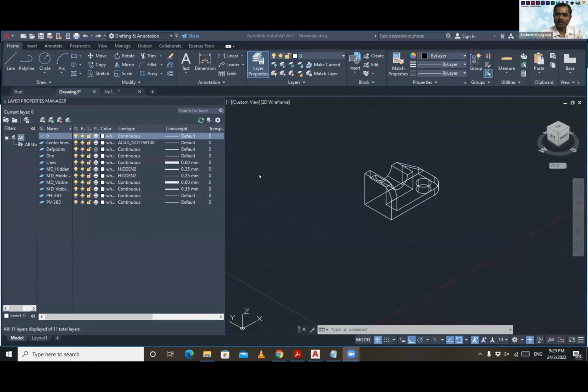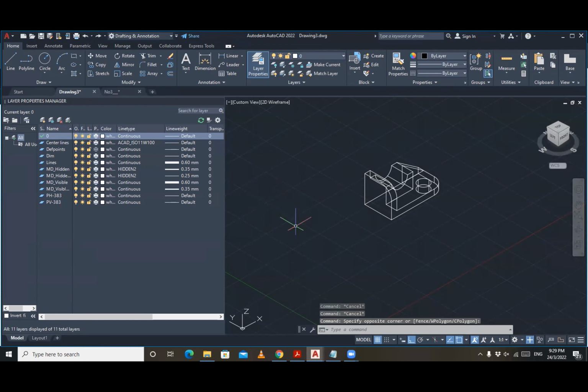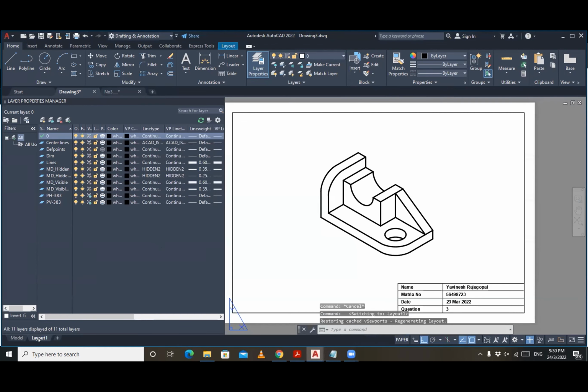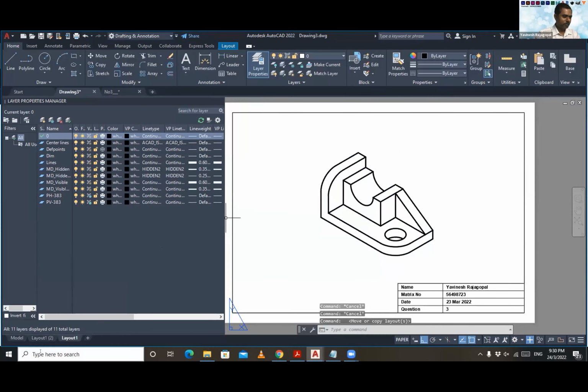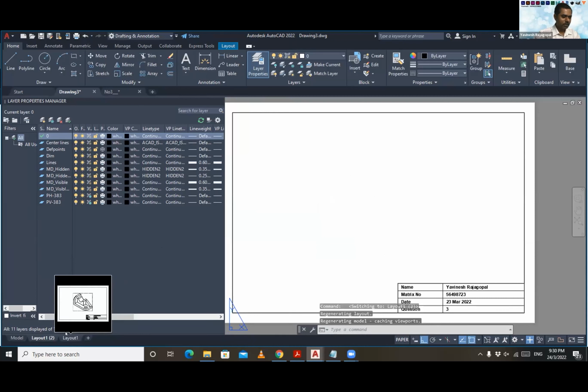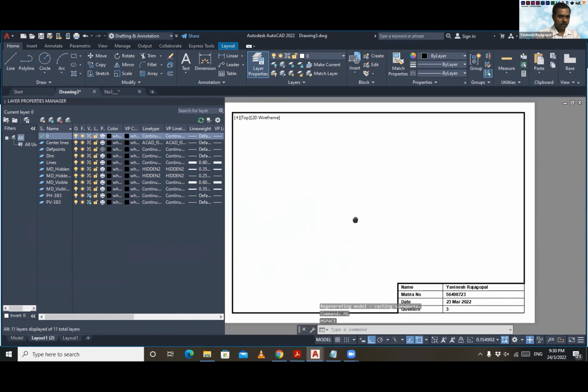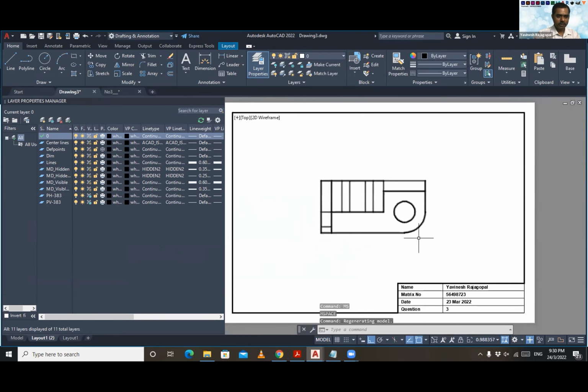Take a look at my screen now. One way is, let me see whether can or not. If I create another layout, let's say I duplicate or make a copy, click OK. Layout 1. At this layout, I type MS. Let's say I have 2 layouts here.